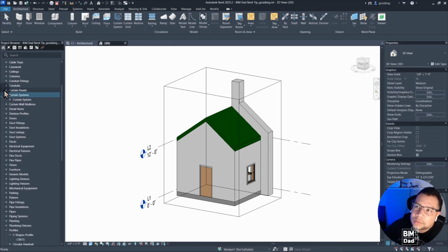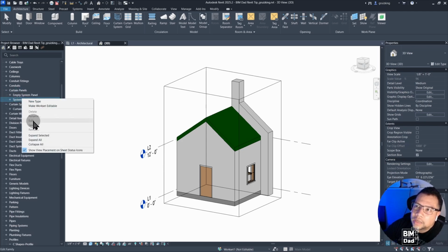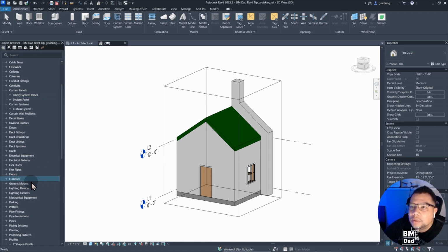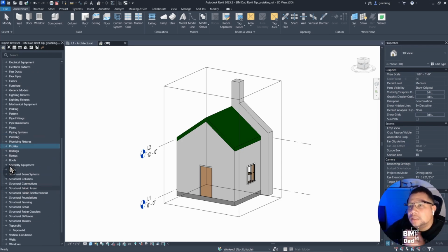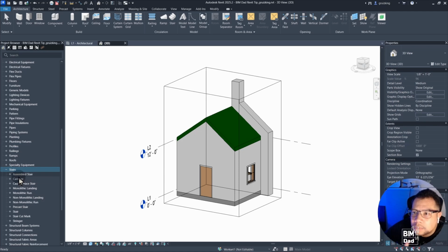System panels down here, right? There's system panel. This is something that you cannot edit outside of the Revit project, but it can be loaded in. It's a weird one. And then if I keep going down, stairs are going to be another one. So stairs are technically system families, and similar to the mullions, they can be made up of multiple components.